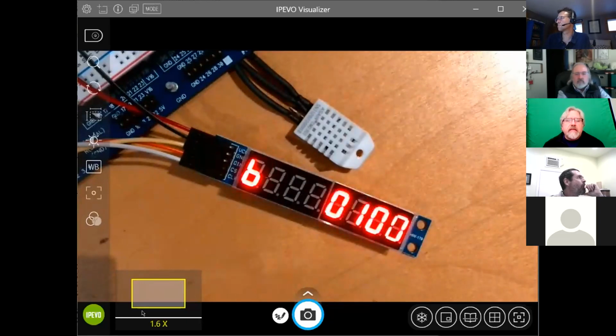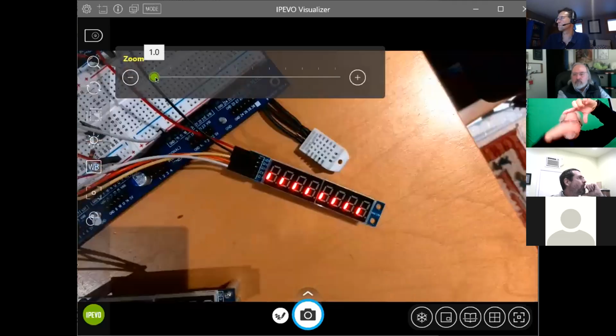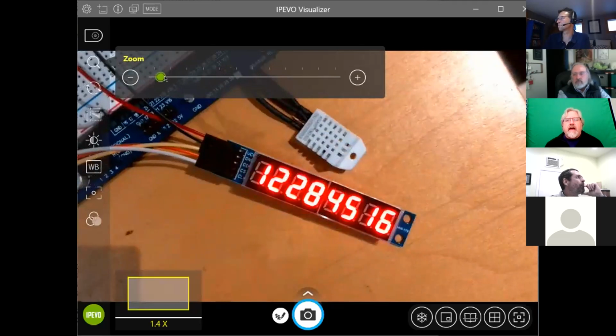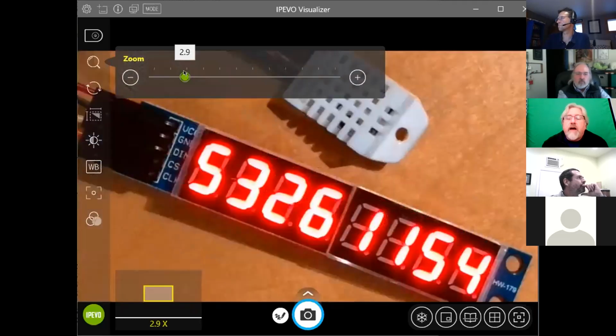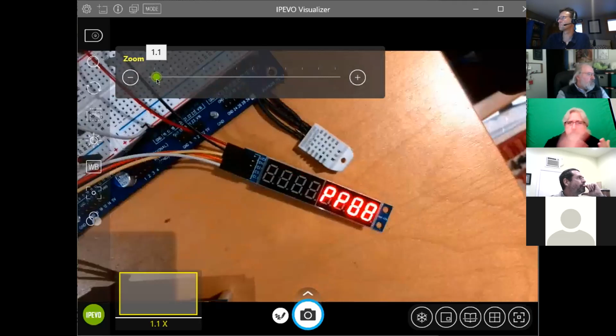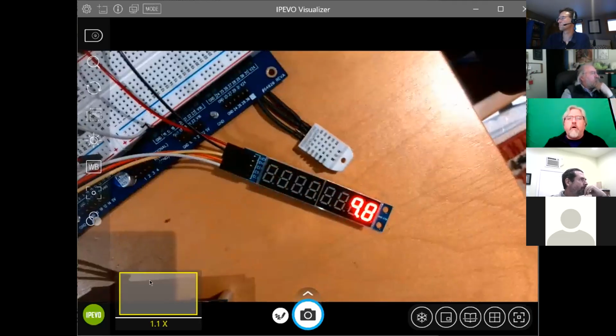You can get these large 7-segment displays, about 6 or 7 inches tall, that have a 595 shift register on them, which I was talking about earlier, and some high current drivers. So you can use SPI code to send the digit patterns out. I made a giant wall timing clock for an escape room in Dallas using a Propeller 1 and really big 7-segment displays.